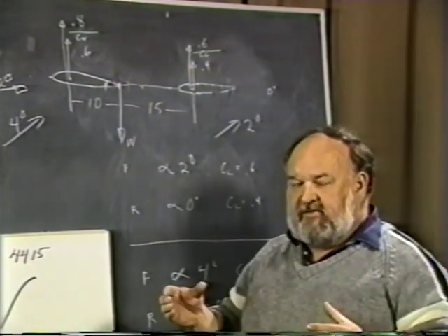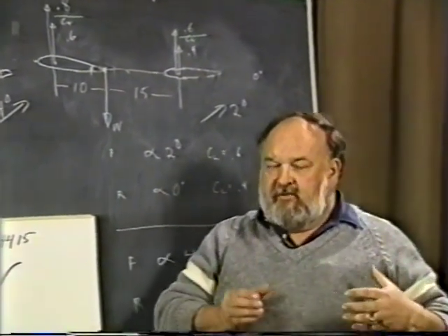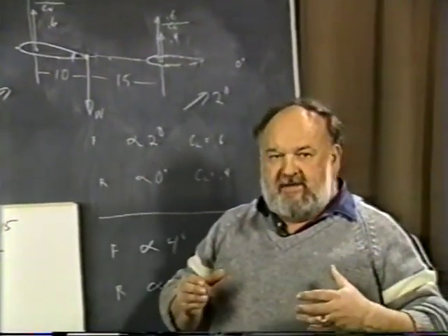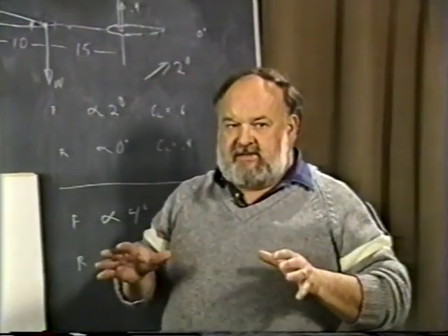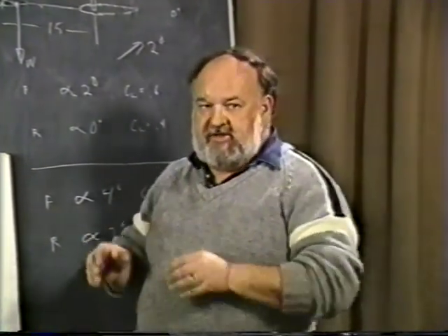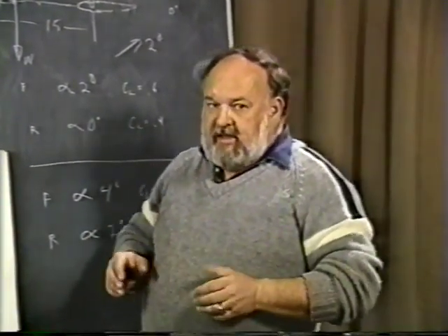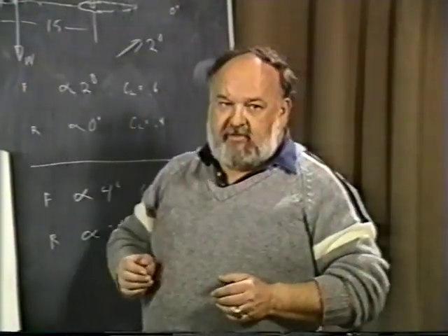You have the front surface, which must be producing lift. You have a rear surface, which must be at a lower incidence, lower angle of attack, so that when a gust condition comes, its change is greater percentage-wise than the change in the front. A normal airplane, this is a large surface. This surface in the back here is relatively small.